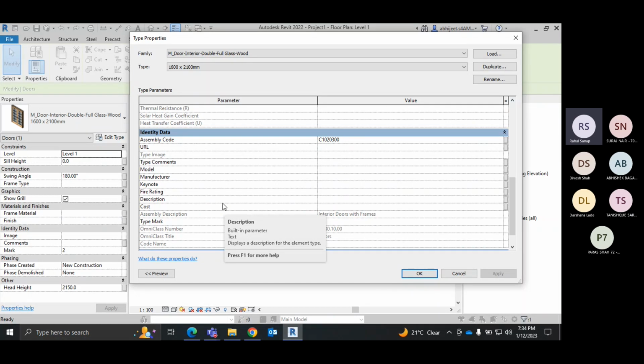Majorly we are developing the drawings on LOD 300 or LOD 350 in Indian conditions. Okay, max to max LOD 400. No one is doing LOD 500, the as-built condition. As-built is done when your entire construction has been executed, and then we add the facility management, green building concept, and sustainability. Those things come under the as-built